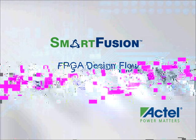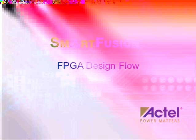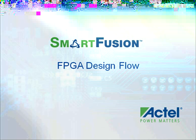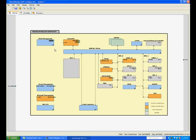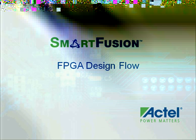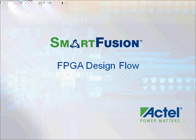When using the fabric, you need to connect the fabric clock pin of the clock management block by right-clicking the FAB_CLK pin and selecting Clear Attribute. Then right-click again on the FAB_CLK pin and select Promote to Top Level. Double-click the clock management block to view the possible configurations, but for this design we will accept the configurator default settings. Click OK when finished.